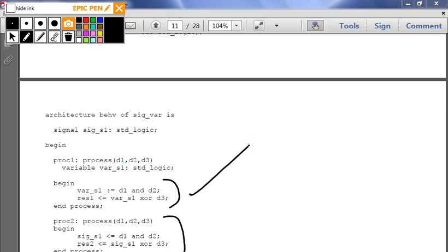Yes? If you're trying to hold a signal like that through the buffer so they end up there at the same time, is there a general rule of thumb? Do you just play with it to see how long it takes? Well, sometimes you want to be able to calculate it. We won't be going too much into depth in this course on design testing and fault tolerance, but sometimes you want to test what's known as the critical path, which is the longest path that you're going to possibly calculate in the circuit.